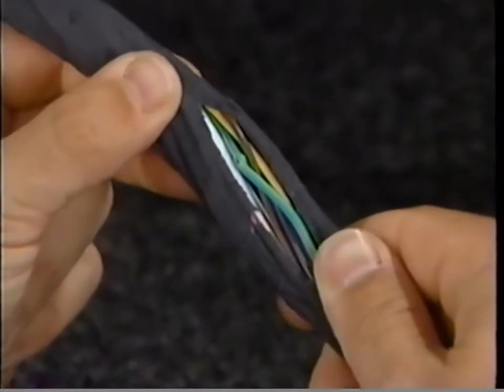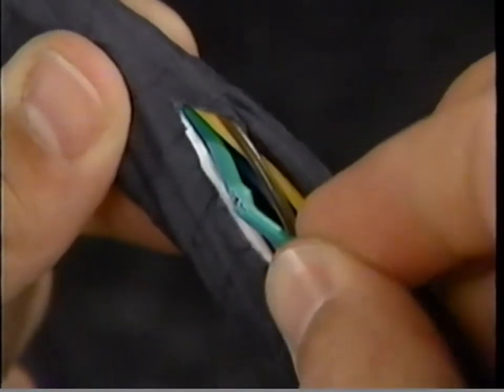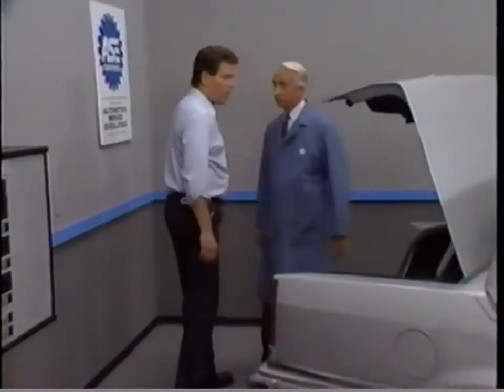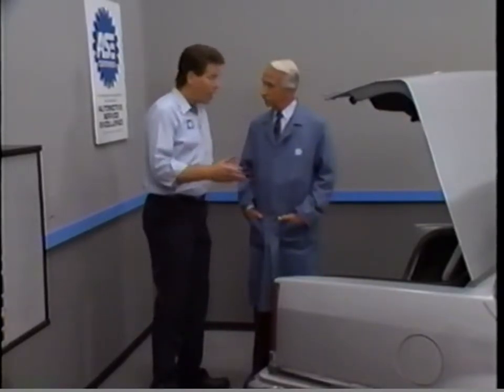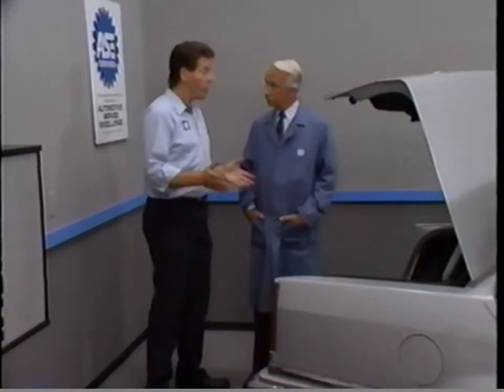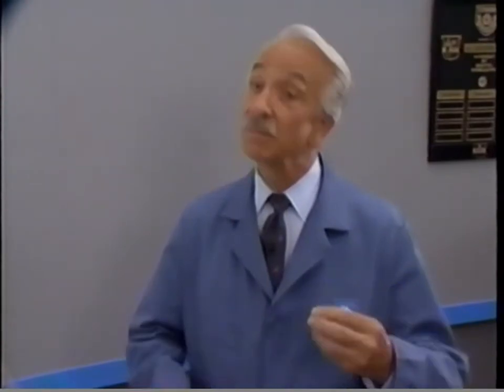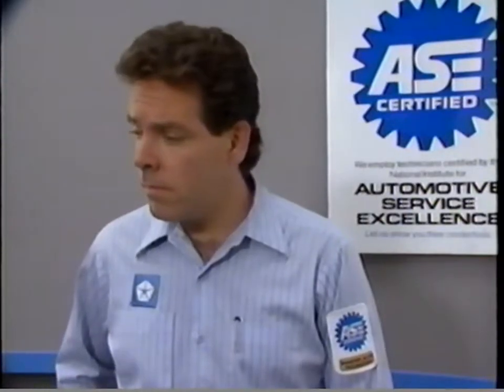Inspecting the harness, we find that a screw has penetrated one of the wires. The harness will have to be repaired. I ran into a shorted harness like that between the radio and speaker, and it caused the radio to fail. In fact, I replaced the radio twice before I realized that the short was in the speaker wire. Well, that's because the short to ground in the harness increases the flow of current from the radio. This short to ground may also cause the radio to shut off immediately, or in some cases after the radio has warmed up. And this may lead you to the misconception that the fault is in the radio.